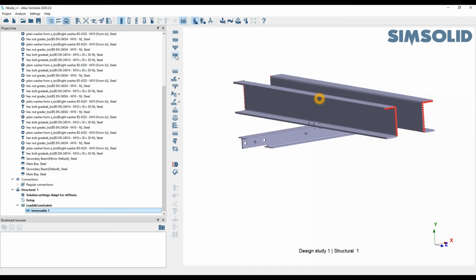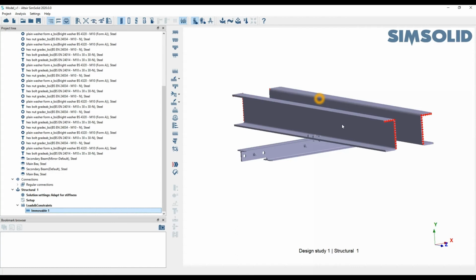Now on this next part, you'll see that we also have a spring support. So this is like establishing an elastic foundation for, say, if something isn't actually properly constrained, but there is a bit of leeway to how much it can move, you can give that sort of elastic foundation in terms of stiffness values in X, Y, and Z.